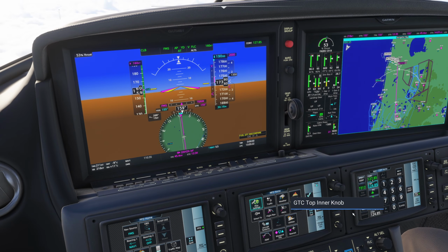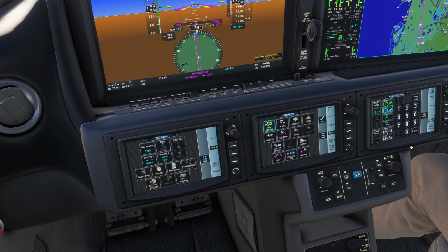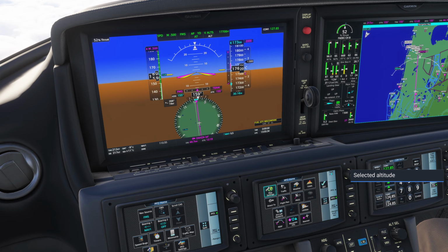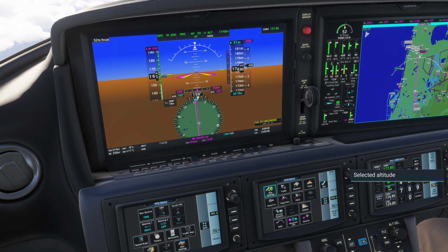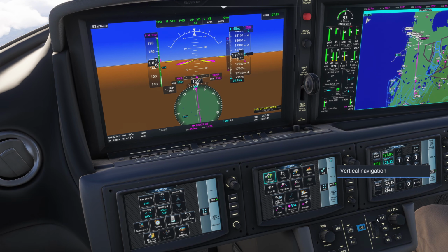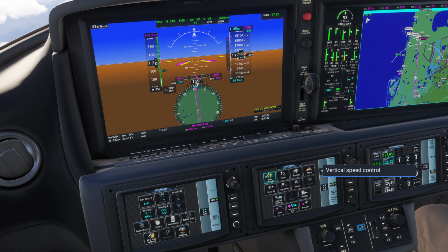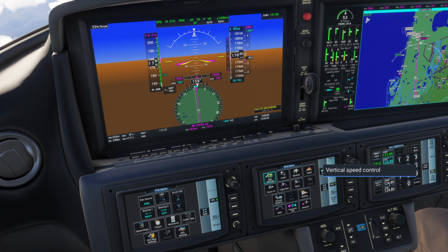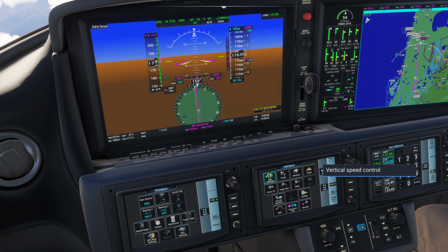So to descend back down, we're going to set our altitude. Let's set it to around 4,500. That's where it says we need to be on our approach plate. So 4,500. And we can press vertical speed, and let's set a good rate of descent. We're going to put our vertical speed bug to the VNav targeted bug, so it will help the plane descend.